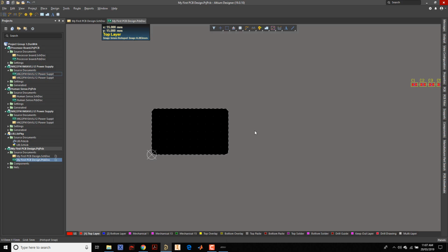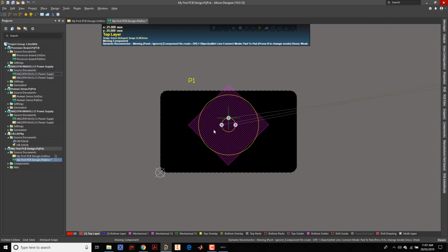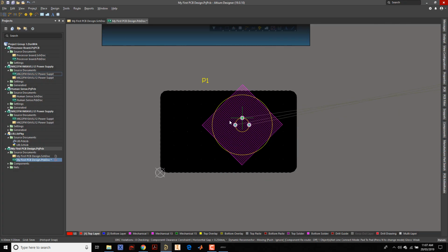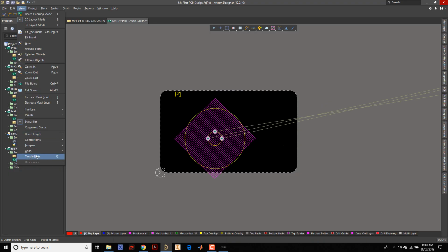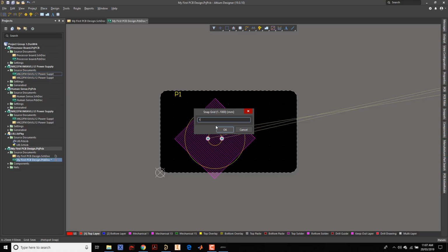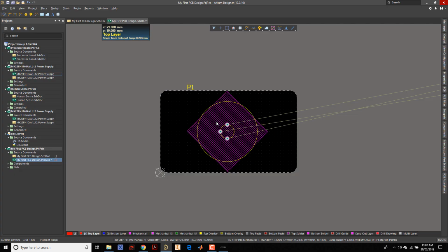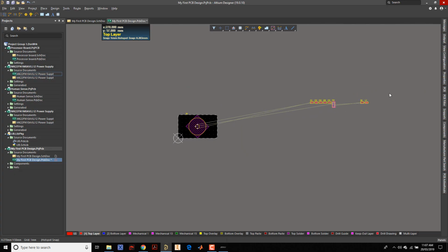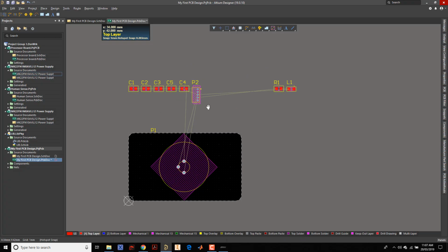Okay, it still looks quite big though. No problem. I'll just drag this and bring it here. Now remember, I set the grid to 5 millimeters. So it will make life hard. I won't get to certain points. So I'll just set the grid to maybe 1 is fine. And it's smoother now. Okay, I can rotate it if I want. See, it's rotating. Good. And I can just drag this and place it anywhere I want. But you need to plan your board carefully.